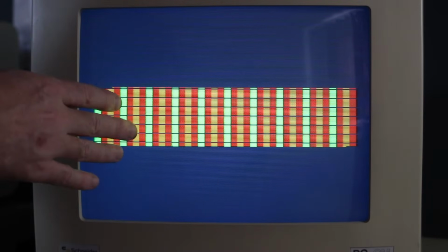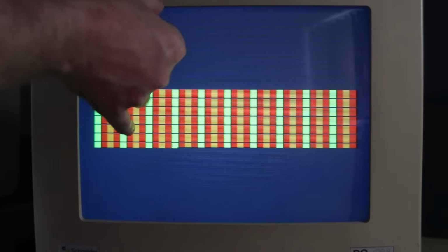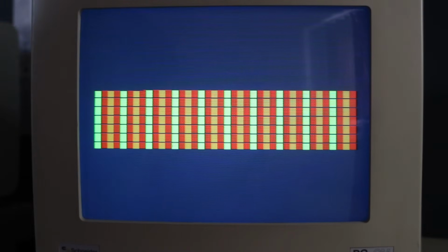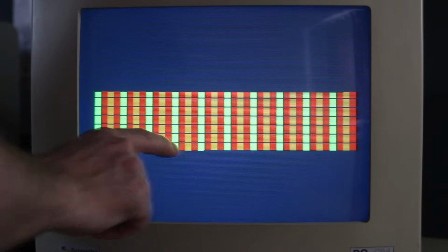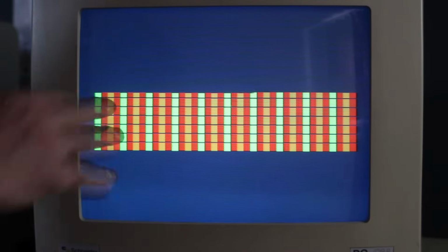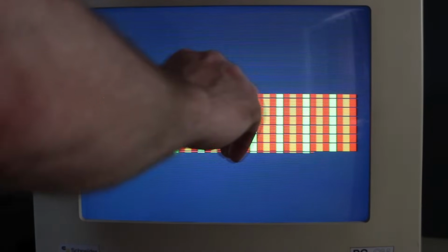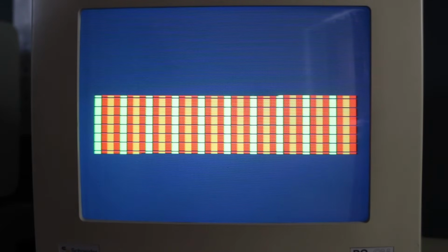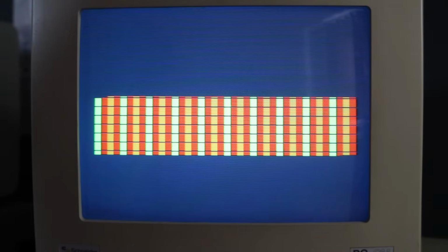So in this particular case, I'm changing the vertical displayed register, which is responsible for the number of characters displayed in the vertical direction. So I'm changing it to one value up here and then back to the original value down here. And because of this natural drift, I'm changing that at a different point every frame, and I'm going to go through all the locations in the frame this way. Now I've actually already been all the way around, and it really didn't glitch at all.